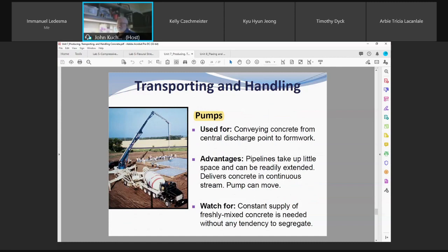Another pump. Yeah, he's parked over here. He's set up. He's got his outriggers set up. The delivery truck dumps it in. He pumps it up and down. The best thing to do is try and keep your boom as horizontal as possible without too many bends in it, because it affects your air. And that's just another matter all to itself.